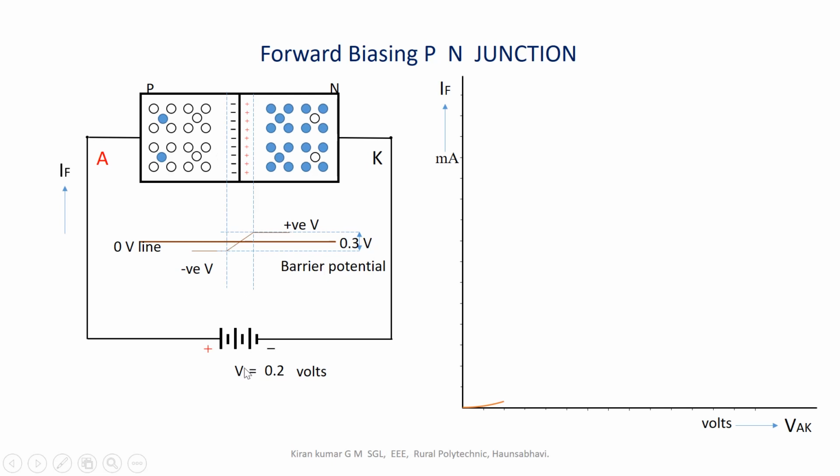With this applied voltage increased, the barrier potential decreased, these electrons are free to cross this junction, creating more current, and in the graph the line reaches a new height, a new point representing the increase in the current flowing at this new voltage level.